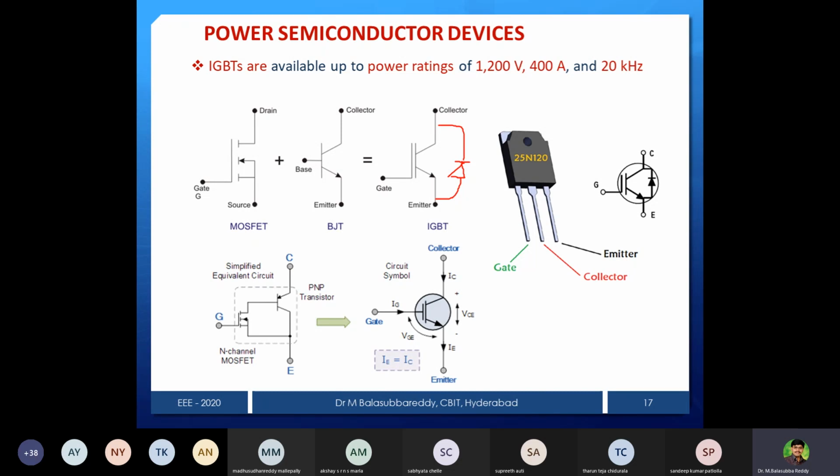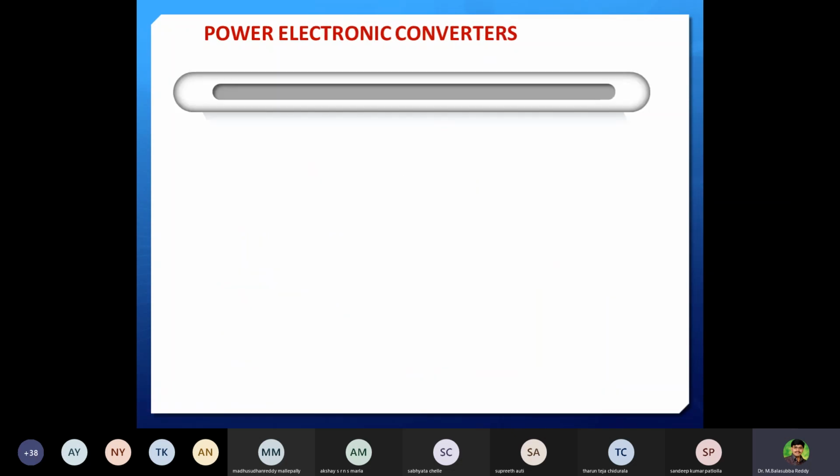There is a DC input, and we can design the inverter to convert DC to AC. That AC you can connect to the application. Instead of DC, you can use input from a solar panel. You can do a project like that. You buy small rating solar panels, design your inverter and control technique. You can use one of the latest control techniques, either a microcontroller or AI techniques, and generate the firing pulses. You give that pulse to the IGBTs and the IGBTs will fire, meaning the inverter will operate. It will convert DC to AC. That AC you can use or you can feed to the grid. So that is what you can do.